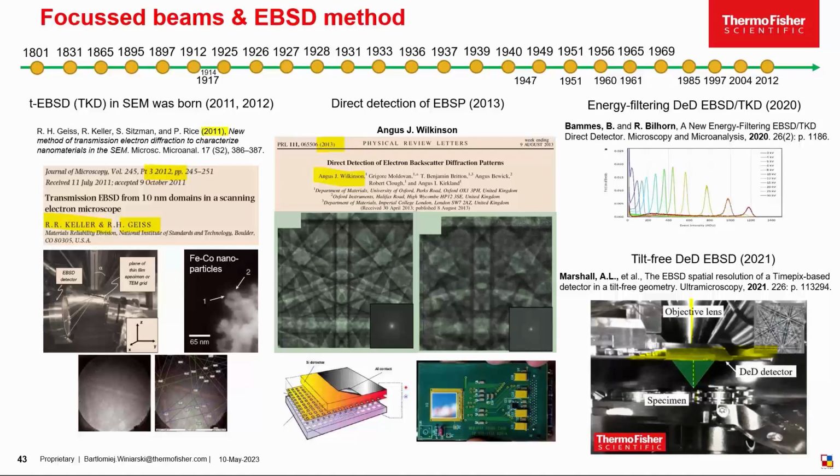In such a configuration, the interaction volume of electrons with matter is symmetric, unlike the largely elongated one for the classical EBSD geometry with 70 degrees sample tilt. Also, the sample size is not restricted by the hardware, thus very large flat samples are now possible to examine.